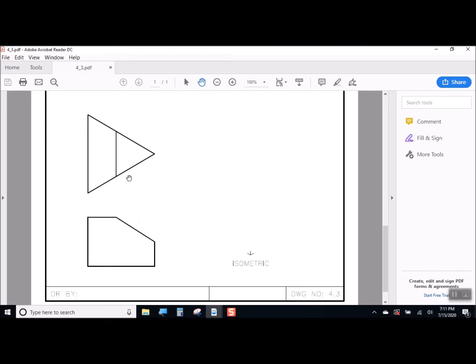This drawing is especially fun and painful because it's asking you to do two different things. This is a very complicated shape. It's actually two shapes superimposed on top of each other. So how does it work? Well, just do this. Figure out what your width is, your height, and then your depth. Then set up your isometric from that point with the proper width, the proper depth, and the proper height.